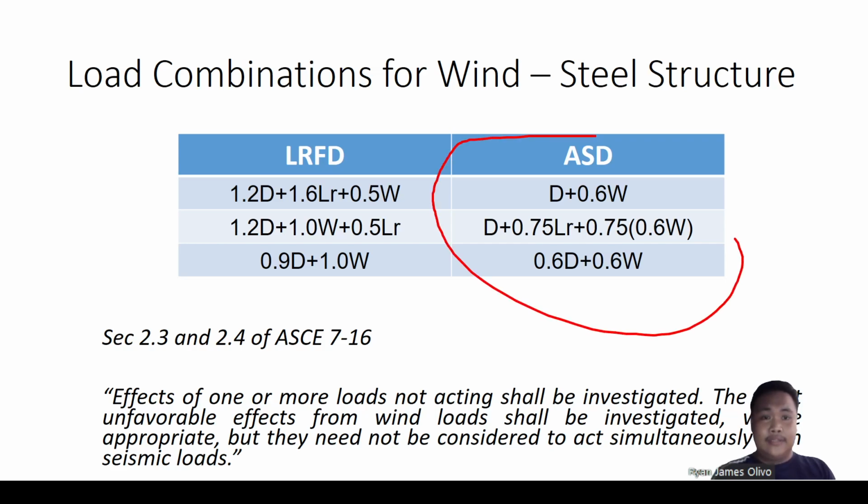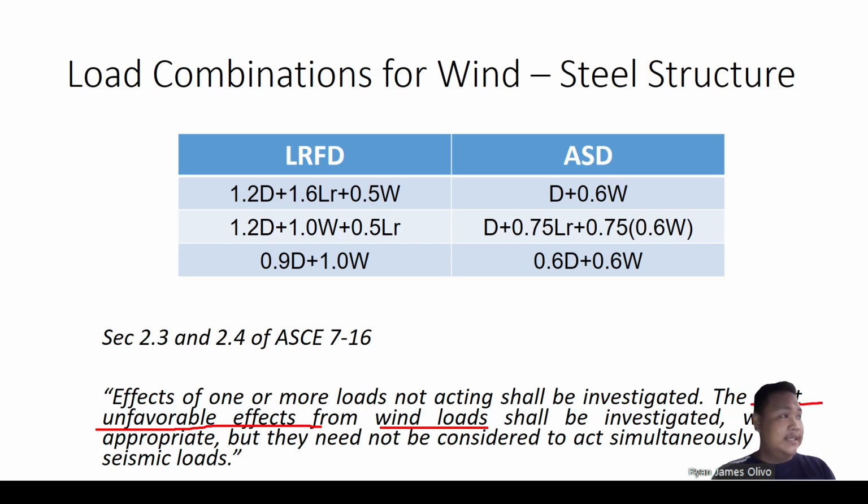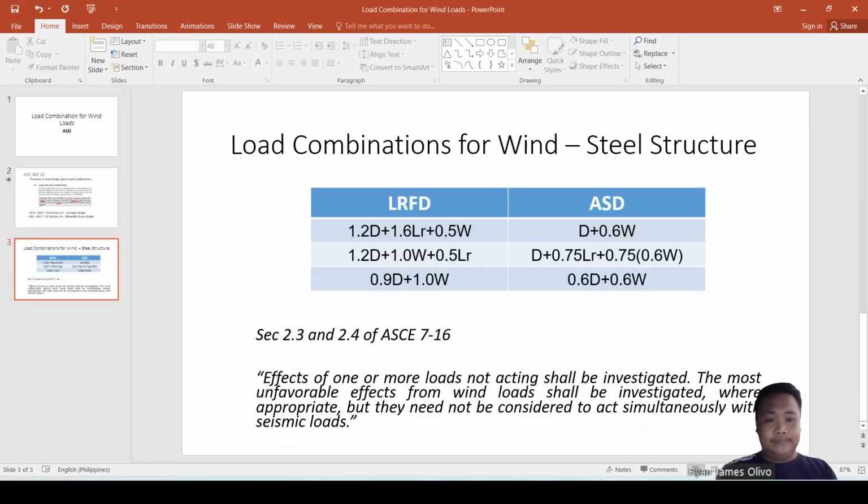Again, I'd like to remind you that we need to investigate the most unfavorable effects from all wind load cases. And we also do not consider that seismic loads and wind loads will act simultaneously. So anyway, let's go to ETABS.